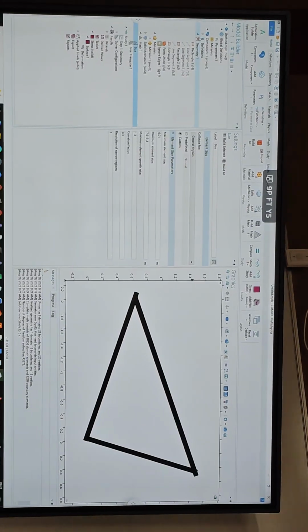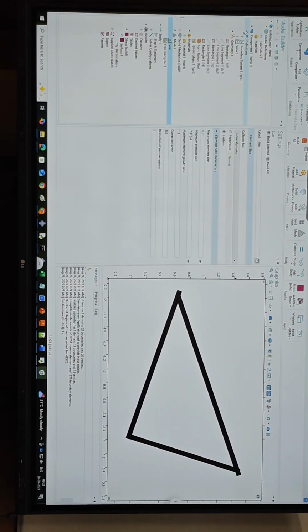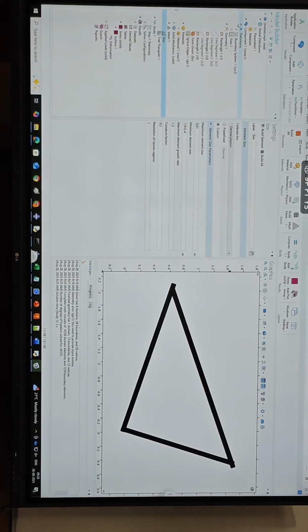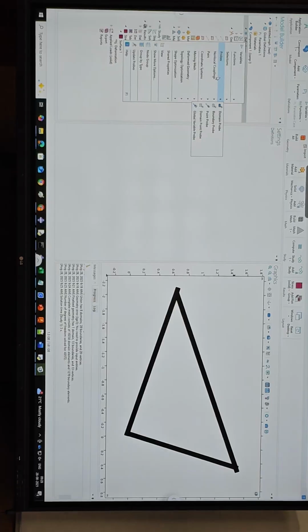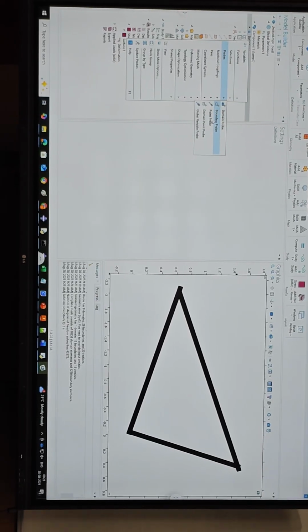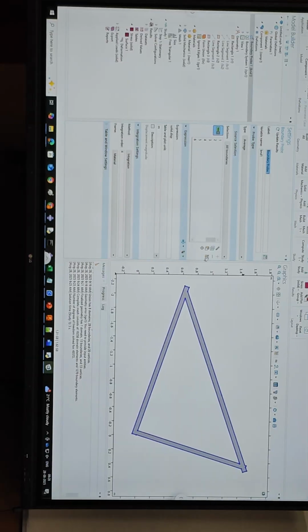So let's say we're giving a load at that tip, and I want to take the displacement from that tip. So we'll go to definitions. I'll right click definitions and we have something called probes here. I'll take a boundary probe. Then immediately clear the selection, because it will default select everything.